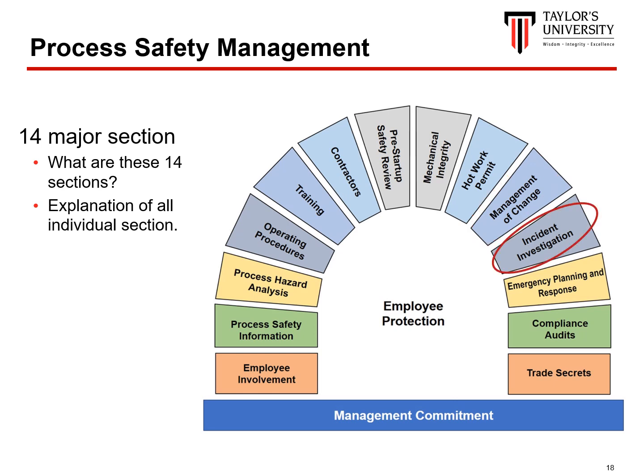The PSM standard mandates incident investigation. Employers must investigate all incidents that have or could have resulted in a major release or accident within 48 hours of the event. The regulations require an investigation team composed of people, including operators who are knowledgeable about the system. After the investigations, the employers are required to appropriately use the investigation's recommendations.